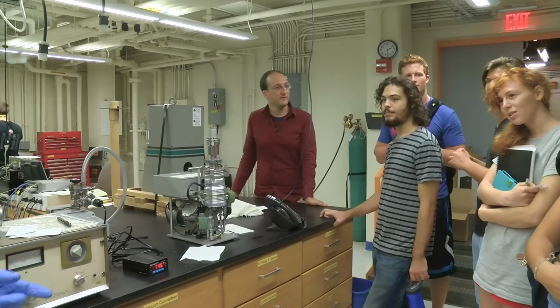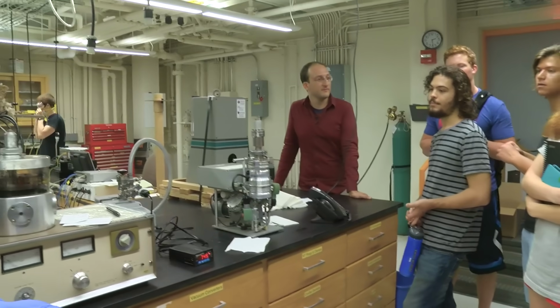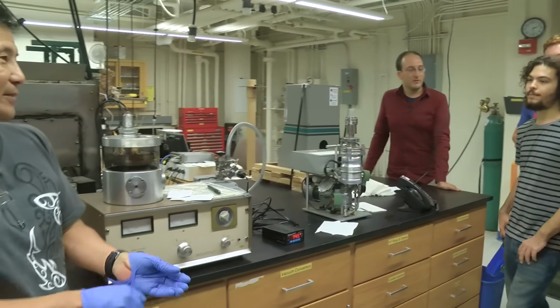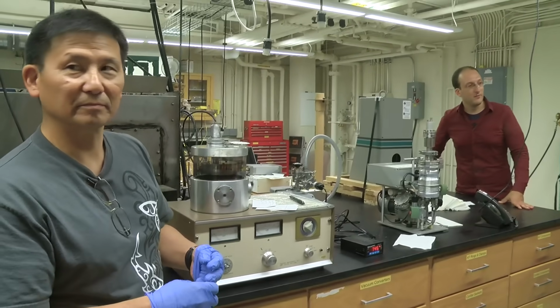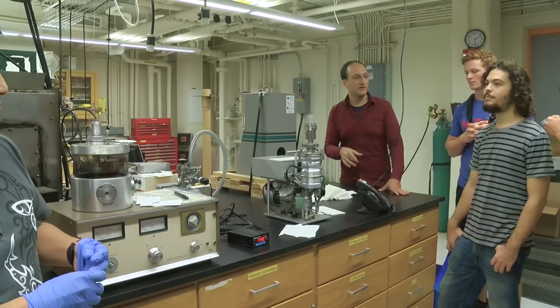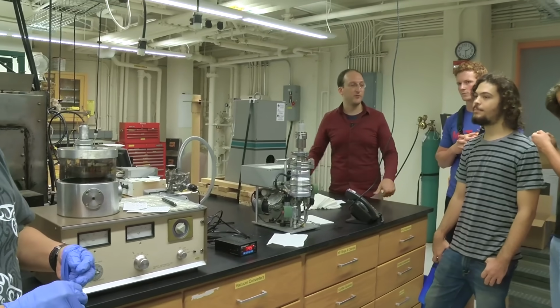It was called a sputter? Sputter coater. It's because the process of the argon hitting the gold is actually known as sputtering, which is the blasting off of surface atoms by energetic particles. It's a controlled form of radiation damage.